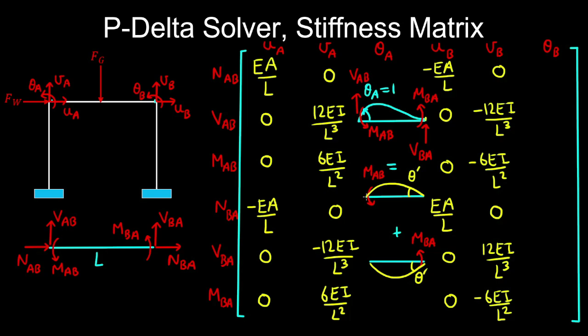So the real bending moment diagram will be MAB on the left and 0 on the right. Remember that in our superposition, we release the fixity, and applying a virtual moment at node B, we will want to find the rotation. Our virtual bending moment diagram looks something like this, with a magnitude of 1. Applying the trapezium method, which I'll let you do as an exercise, we get theta dash is equal to MAB by 1 by the length of the beam on 6 EI.